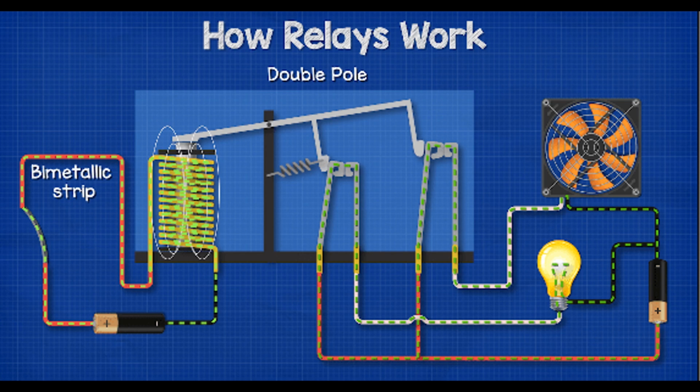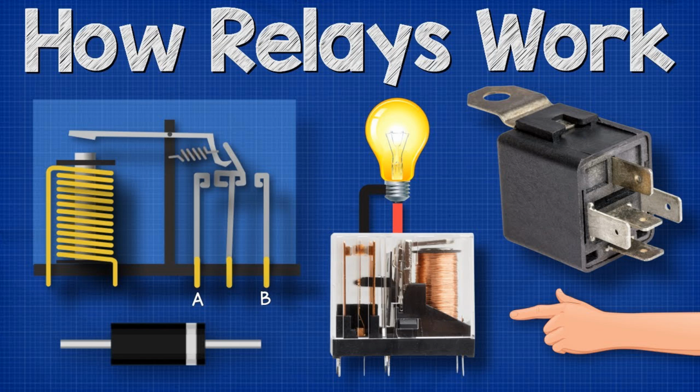Window treatments. Relays are employed for controlling motorized blinds, shades, and curtains in smart homes. They enable the remote opening/closing, tilting, and scheduling of window treatments to manage natural light, privacy, and energy efficiency. Relays can be integrated with light sensors, temperature sensors, or smart thermostats to automate window treatment adjustments based on environmental conditions or user preferences.